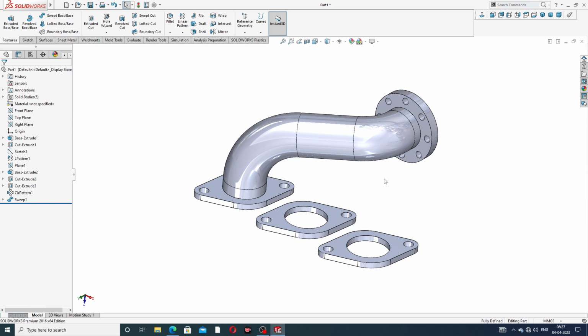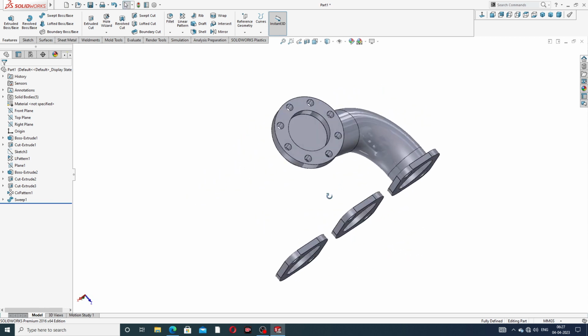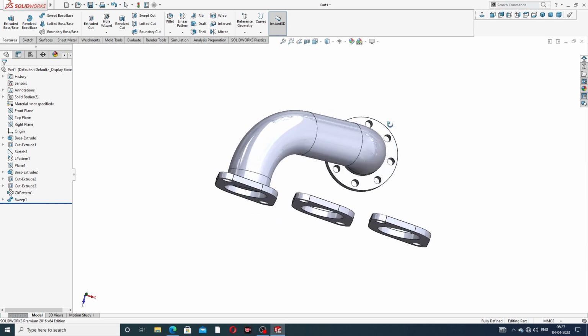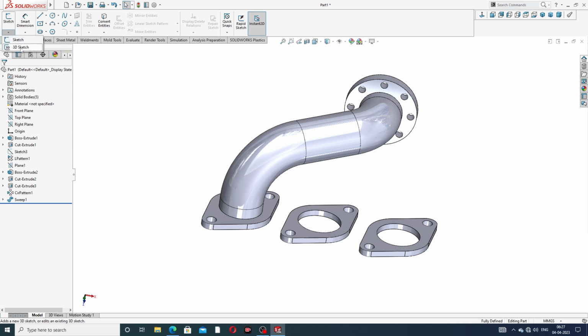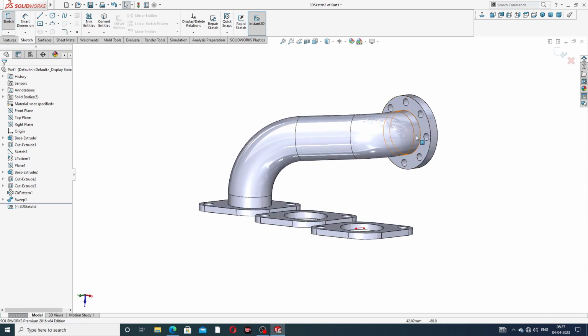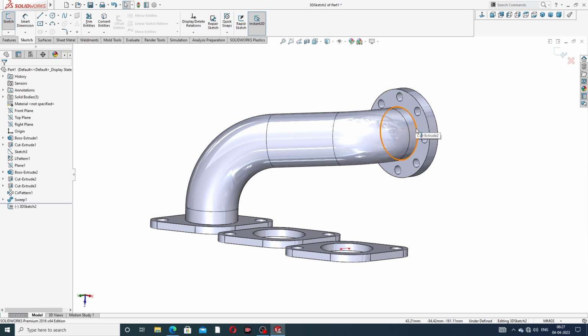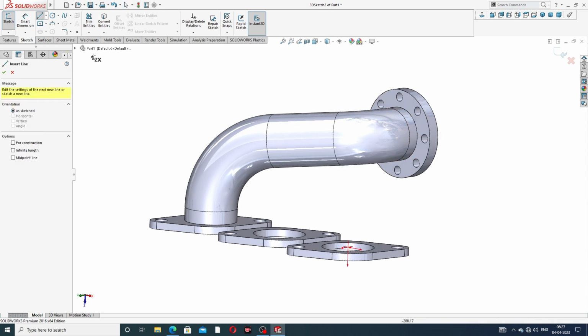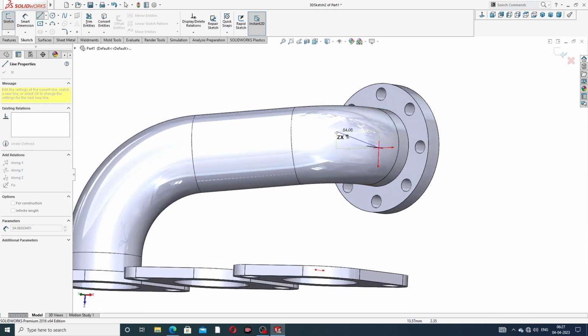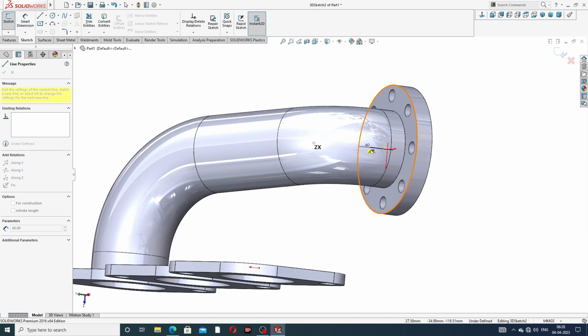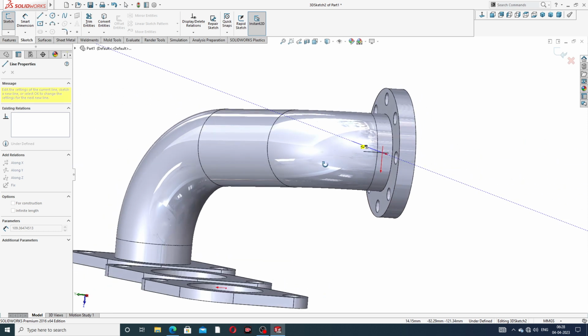Okay, this is looking very nice. Same here, next is drawing with a 3D sketch, and again select this line. This is correct, but this point is vertical and not mentioned here, so press Tab and then use a vertical line.